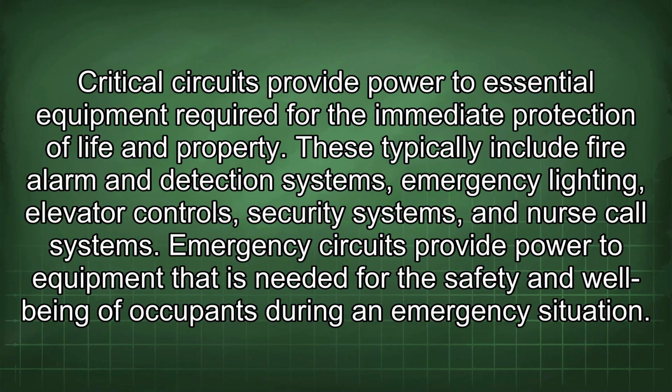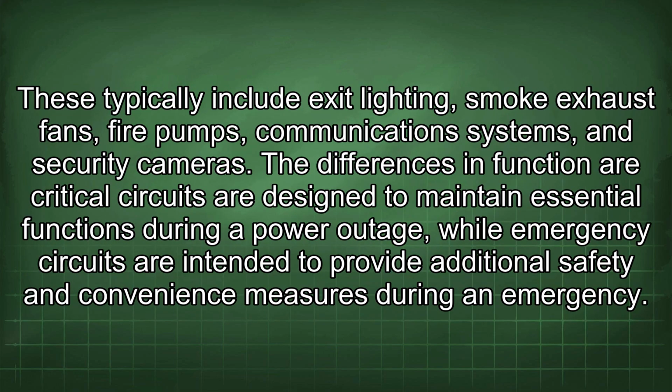Critical circuits provide power to essential equipment required for the immediate protection of life and property. These typically include fire alarm and detection systems, emergency lighting, elevator controls, security systems, and nurse call systems. Emergency circuits provide power to equipment that is needed for the safety and well-being of occupants during an emergency situation. These typically include exit lighting, smoke exhaust fans, fire pumps, communications systems, and security cameras.